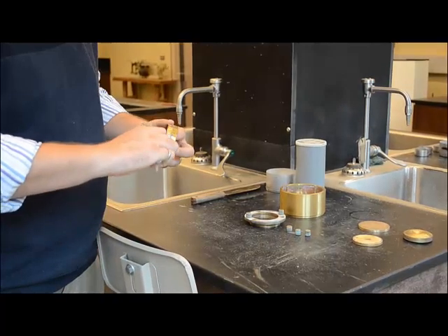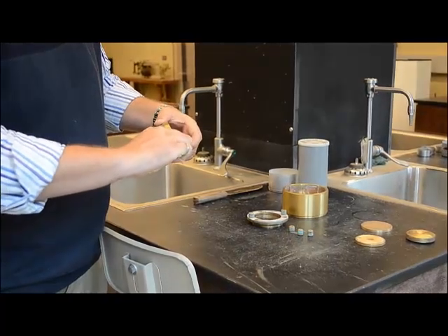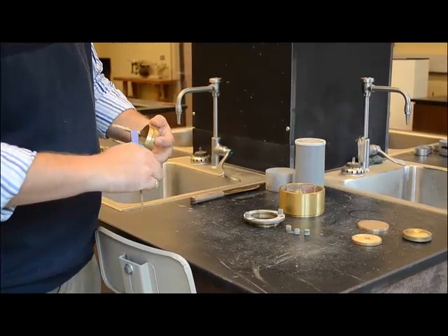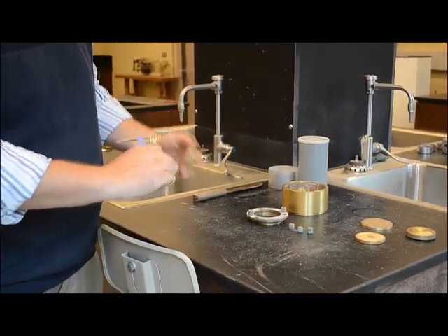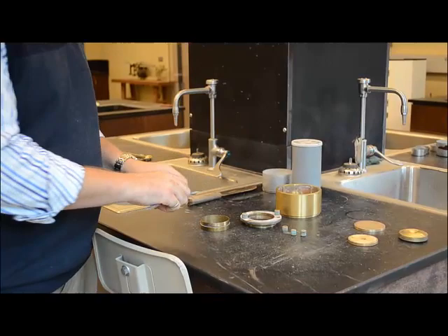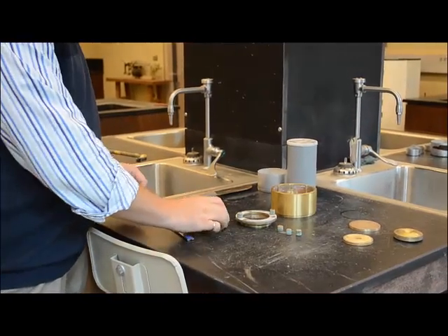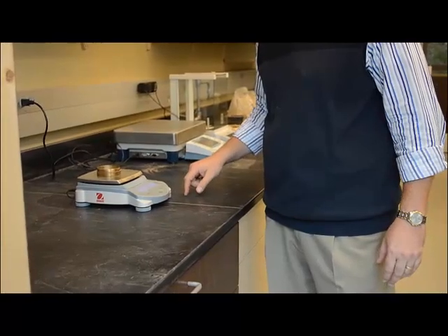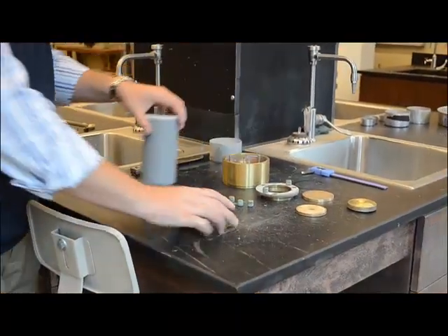And typically this one here is about 2.5 inches diameter and about 3/4 of an inch tall. It's probably a little bit more than that. It's probably about 0.77 inches tall. But get the measurements in about 3 locations. Take an average, and then you want to get an empty weight of that cutting ring too, because you need to know what the actual weight of your sample is so you can determine what your density is.